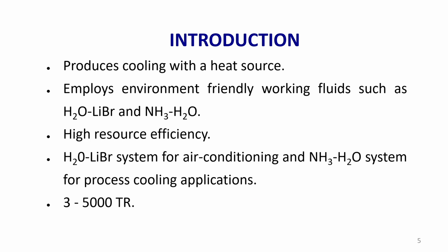Of course, the COP of these systems is high. We have got systems with COP up to 8, 9. The average COP is in the range of about 3 to 4 or 4 to 5. So, performance wise there is no doubt. Of course, from the viewpoint of environment, most of the refrigerants which are used are polluting the environment. So, either they contribute to ODP or GWP or both. So, what is the alternative for this system?